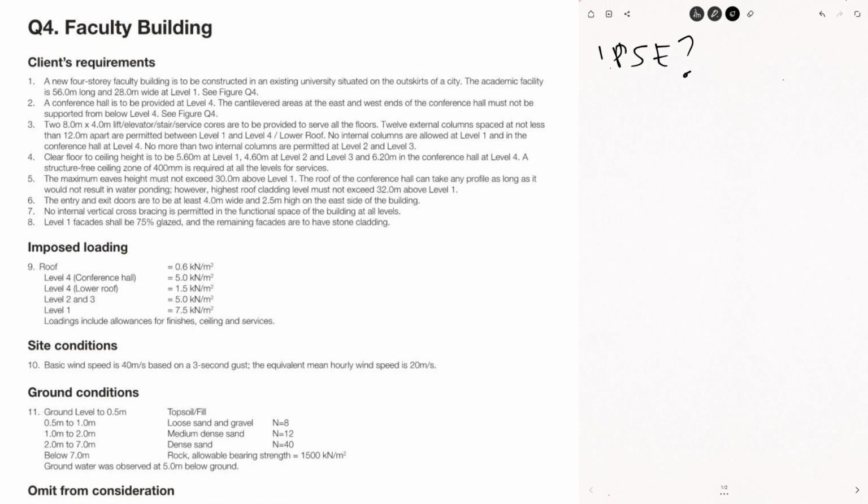They generally are those that are singular to the structure, not columns or beams or the floor itself. So generally cantilevers. Whenever you have a cantilever, that would be one of them. Then if you have large spans. The third one would be if you have any transfer structure. Definitely that's one of the principal ones.